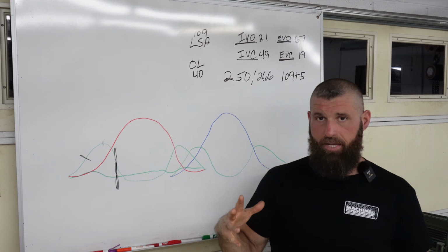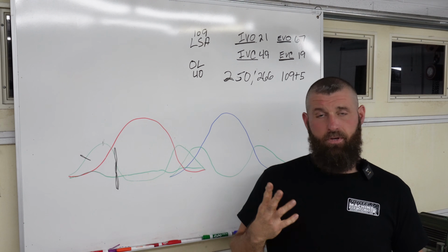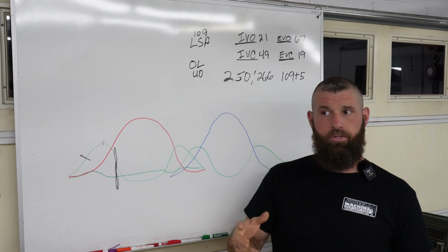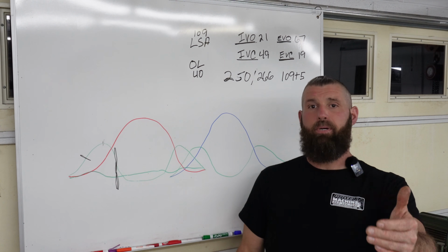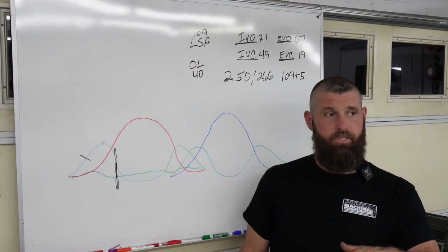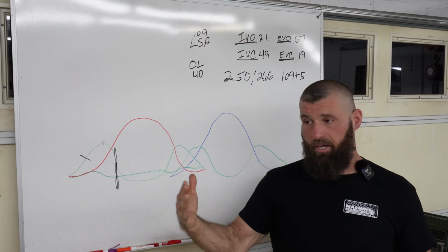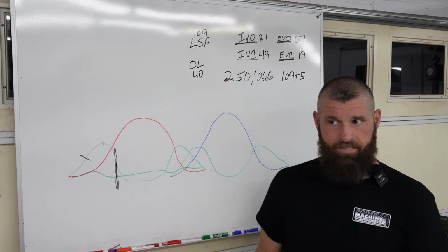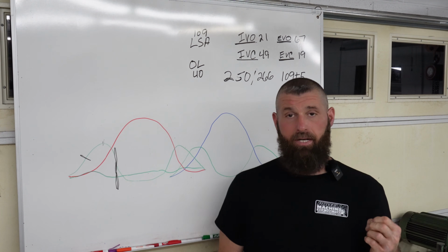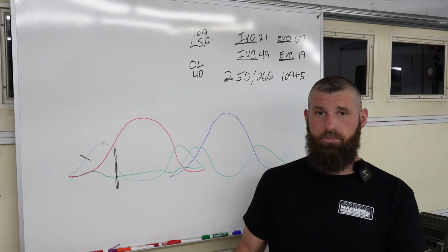So most of the time, whatever the math says, if the math says 245, we're going to actually grind a 249, a 250, a 252. It just depends on the application, the RPM, the spring pressure. The more spring pressure, the bigger we got to make it because the system is deflecting. And I didn't realize till I seen the Spintron data how much the system is deflecting, even with monstrous push rods.